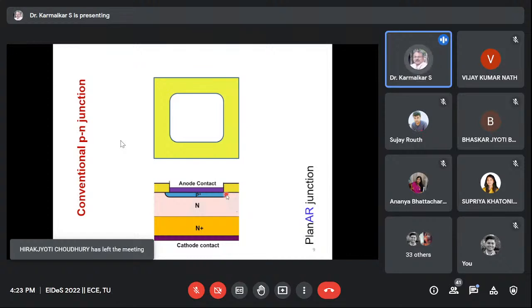Because from your 12th standard physics understanding, if you recall, it was pointed out that from sharp contacts, a high field is possible, right? So same thing here, sharpness is nothing but curvature. So here fields can become high and therefore breakdown voltage reduces.